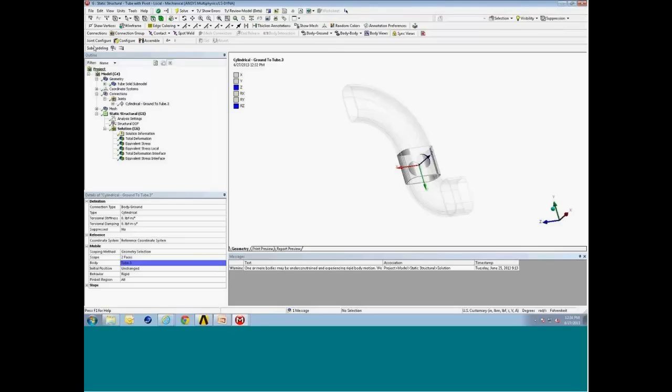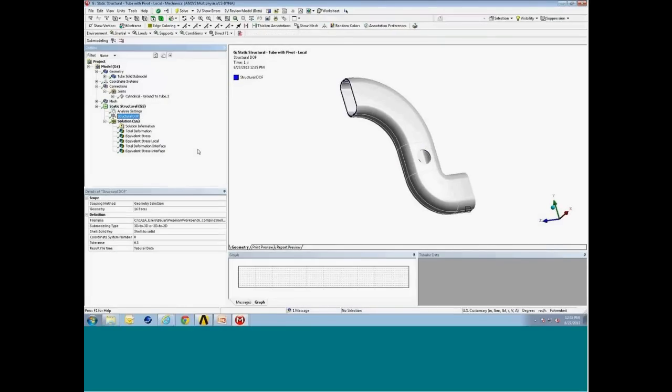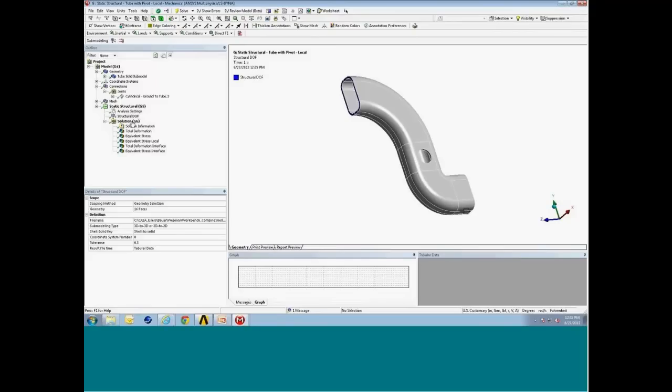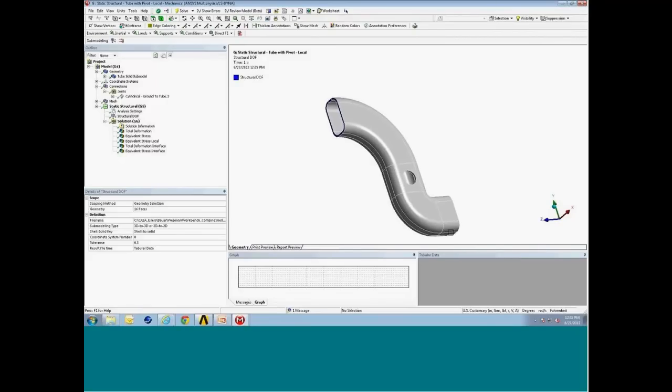When you have installed that extension, you see the submodeling menu. With this submodeling menu, you can transfer the temperature conditions and the structural degrees of freedom. So I've inserted a structural degree of freedom in the outline tree, and this essentially defines how we're transferring the cut boundary location. So with this, let's walk through how we're transferring the boundary conditions.